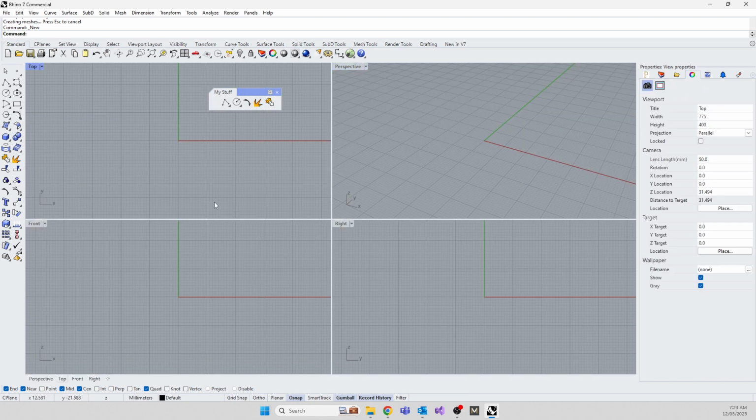If I wanted to bring that file back into Rhino, I could open it. But open would delete everything I have in my Rhino. It's saying I want to close what I'm working with now, and I want to bring in something new. Import will bring something into what you already have. So in this case we want to use import, so the command would be import.